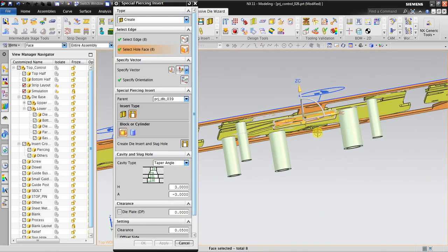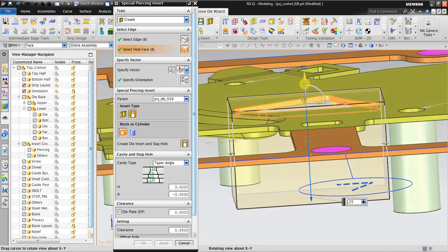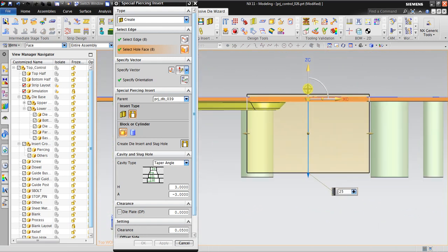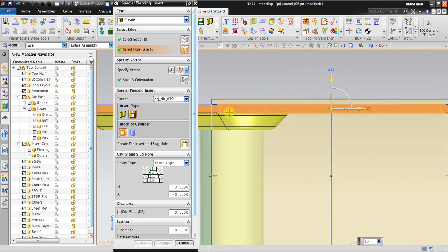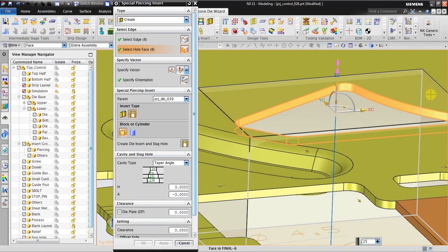Now for example, if I insert about 25 also, the trick in here is you must put this box slightly higher than the object, so it will create a closed surface in here but hollow inside.